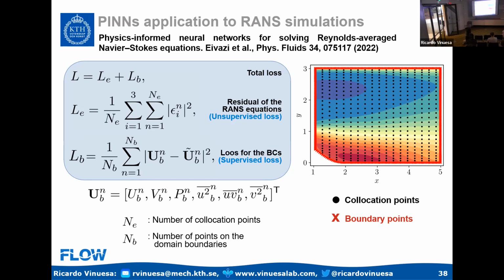So we have tried our PINN simulations with OpenFOAM, and the computational cost is very similar, with the advantage that in a RANS model, you need to have, well, basically the model for the Reynolds stresses. So that gives you an error. With PINNs, no. With PINNs, you have very high accuracy also in the Reynolds stresses. I'll show you some of the results in a minute.